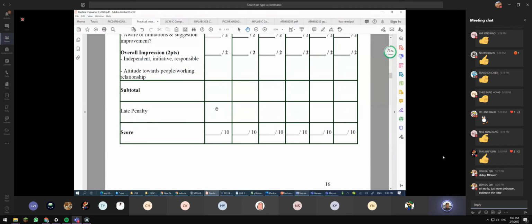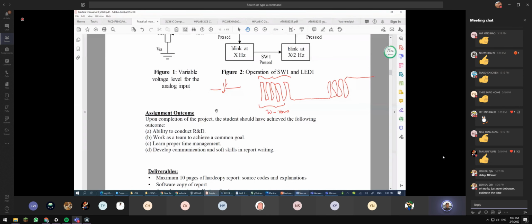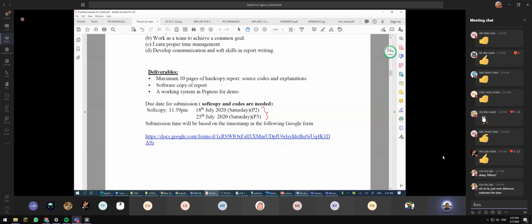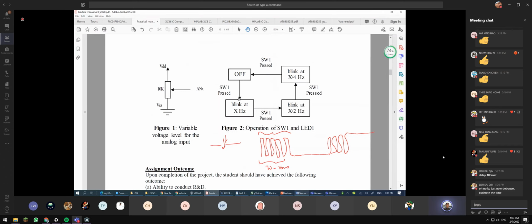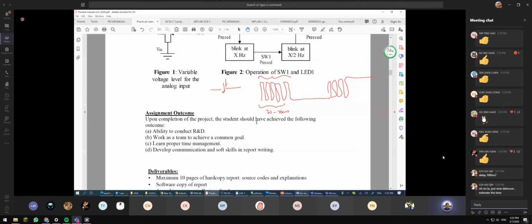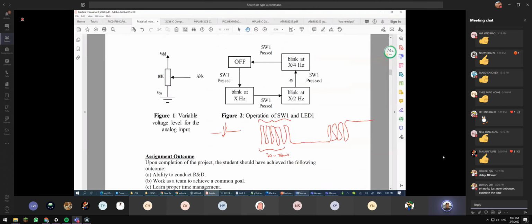So any questions you would like to ask, again, I open this, whether you're using ESP32 hardware. If you're using ESP32 hardware, you do not need Proteus, or you just do everything in Proteus. I believe that a lot of people will choose Proteus. Why? Because in Proteus, you can't even simulate the debouncing problem. 2 switch press at one time, 3 switch press at one time. But I will change this to the sliding switch. I want to make sure if 3 switch press at one time, what will be happening. When I release 1 and release 2, what will be happening? There's a lot of unusual situations that occur, even though it's just a push button switch.